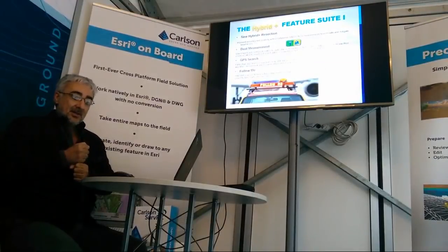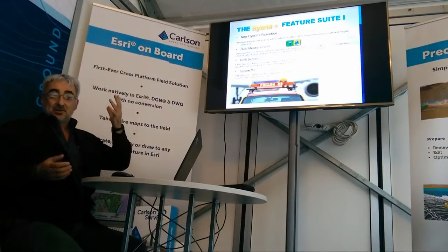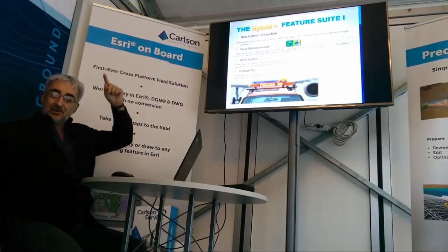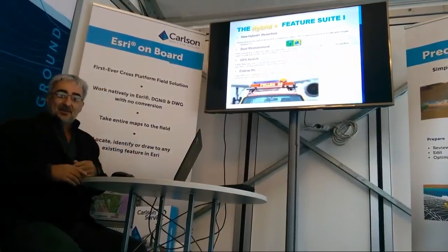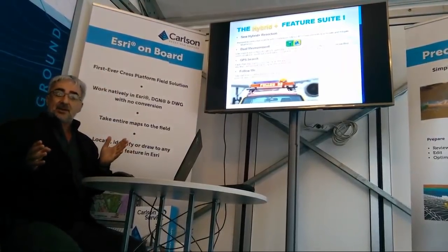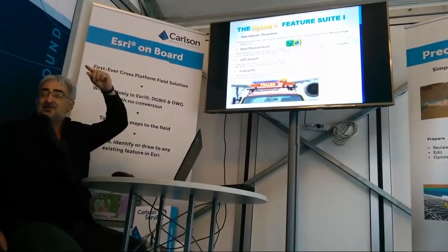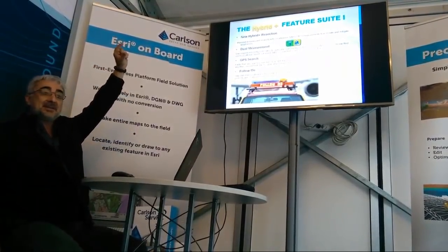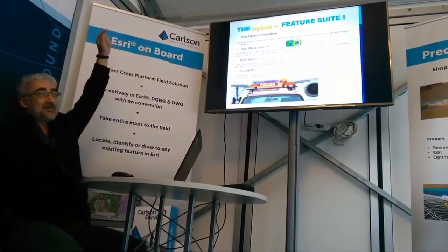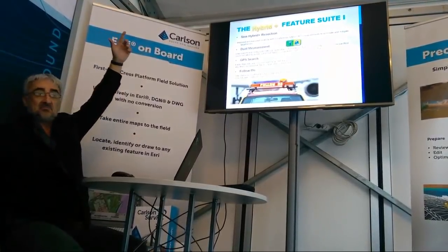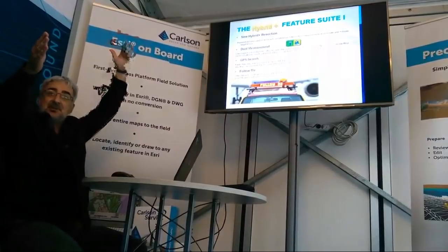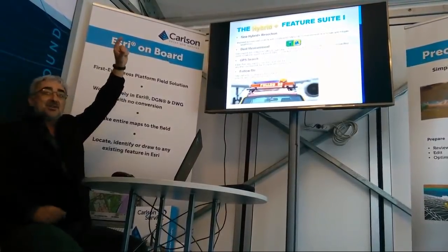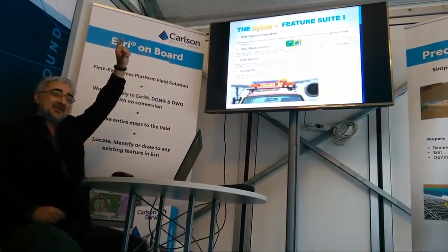And second, the errors for leveling when you're using a pole are totally reduced, or I would say removed, because the 2 meters high is no longer there, it's virtual. Because the real height is the distance between the prism and the phase center of the GPS, 6 centimeters in that setup I have here. So what is the leveling error in 6 centimeters?